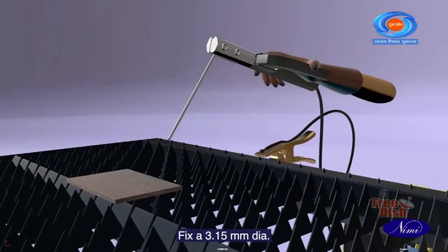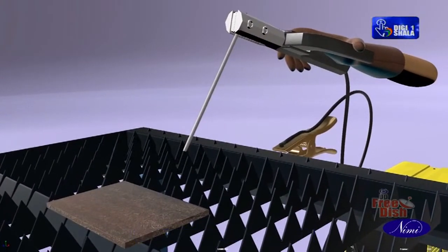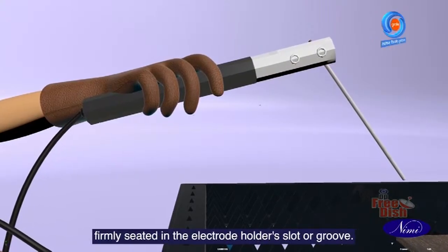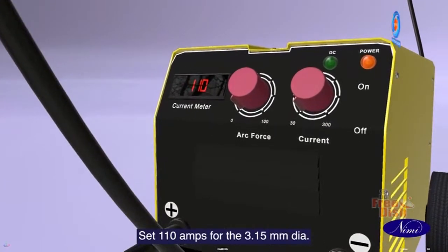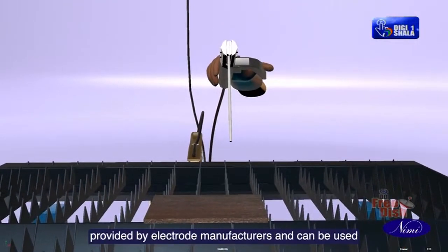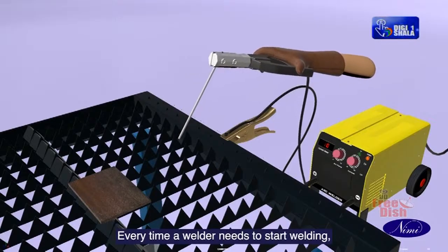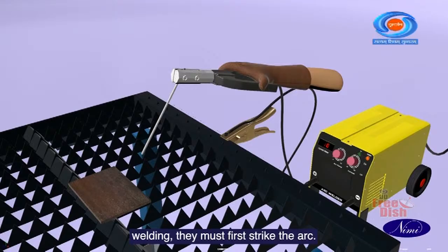Fix a 3.15 mm dia medium coated mild steel electrode in the electrode holder. Make sure the flux coated electrode's bare wire end is firmly seated in the electrode holder's slot or groove. Set 110 amps for the 3.15 mm dia electrode. The current values for various size electrodes are provided by electrode manufacturers and can be used as a reference when setting currents. Every time a welder needs to start welding, change an electrode or stop an arc while welding, they must first strike the arc.